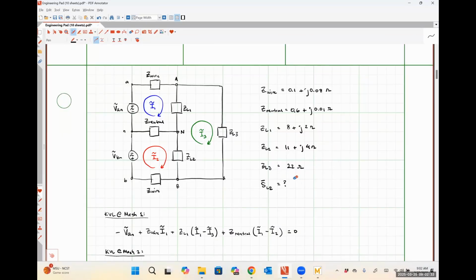All right, so you guys are quiet this morning, so I'll talk our way through things here really quickly. So I want to define a couple of things here. I'm going to define them in purple, I guess. So let's say that this is the current that's flowing through that impedance. So I'm going to call this IL2, right? And this will be the voltage drop across that impedance, which I'm going to call VL2. So according to our definition for complex power, we could find this as VL2 multiplied by IL2 conjugate.